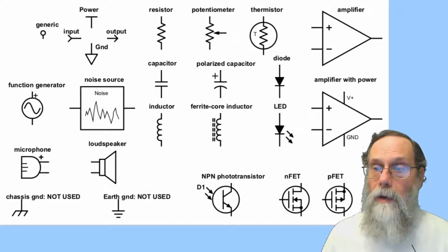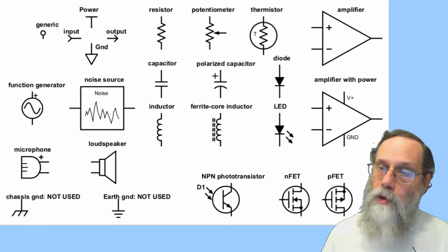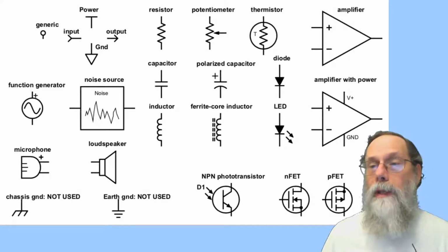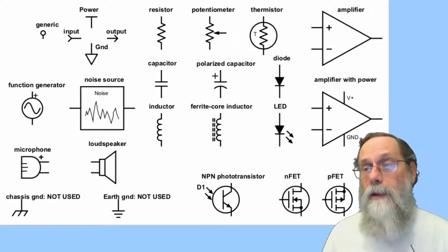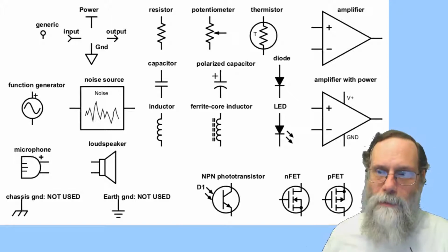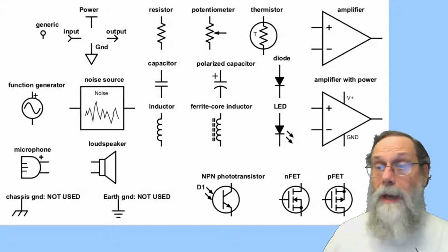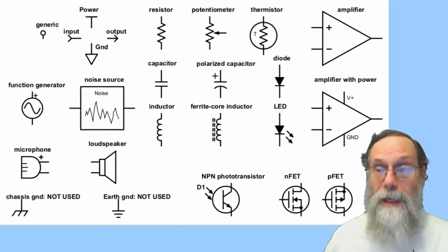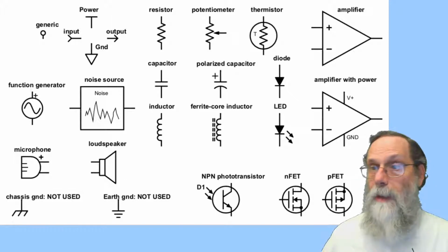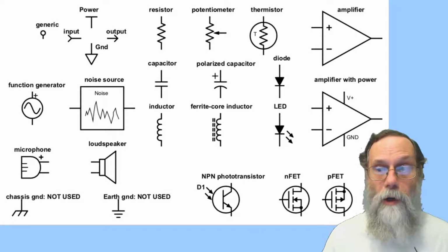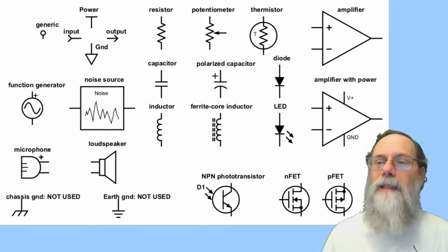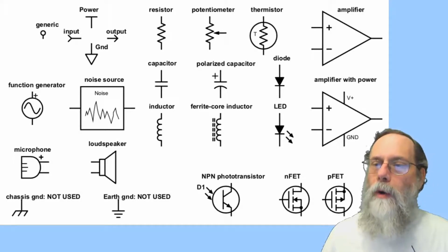And the schematic diagram encapsulates the design you were trying to build. And so one can then look at the schematic and say, this looks like it ought to work. And you can then look at the schematic compared to the thing you actually built and say, wait a minute, this schematic doesn't match what you built. Your implementation is wrong. Other times you look at the schematic and the implementation and say, those look like they match. Maybe there's something wrong in the design. It helps you kind of narrow in where the problem might be.